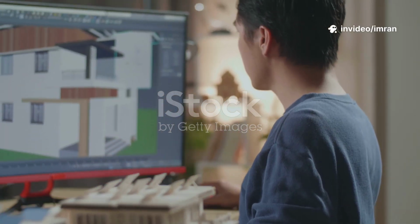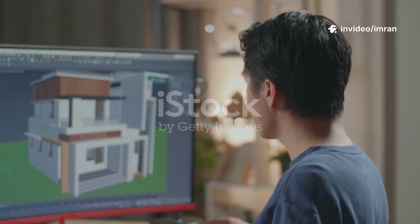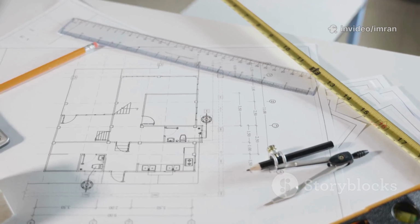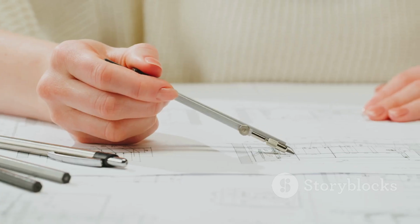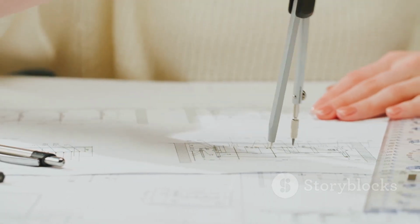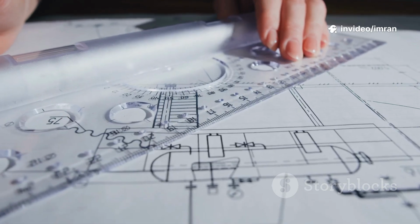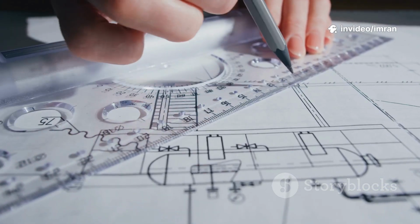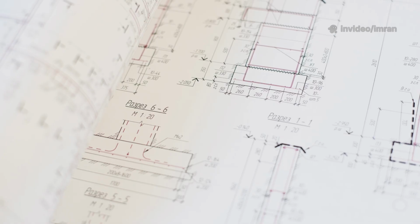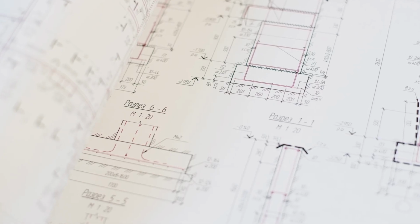Now that you are comfortable navigating the AutoCAD interface, it is time to start drawing. The most fundamental building block of any design is the humble line. The line command is the first and most important drawing tool you will learn. You can access the line command by clicking the line icon, or by typing the letter L into the command line and press enter. AutoCAD will prompt you to specify the first point.